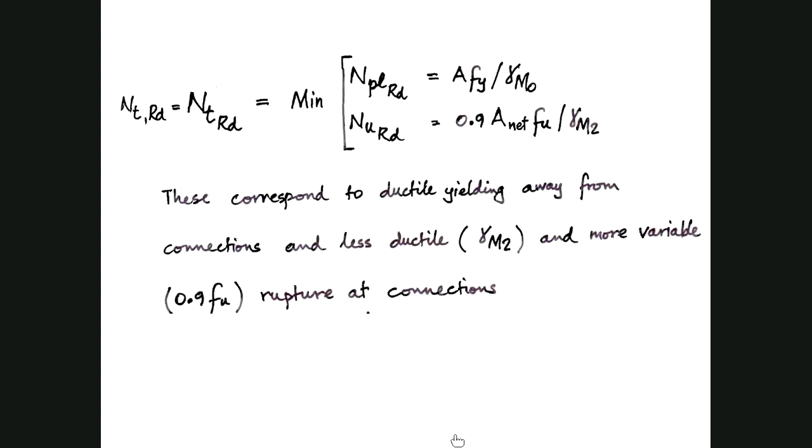Okay, so here's the first general mistake that a number of people made. In the first assignment that you did, people calculated the plastic resistance using this formula here, and calculated the ultimate resistance at the two cross sections. So the cross section basically straight down, which is one hole, and the cross section where you go staggered because of two holes, because of the staggered bolts in there. So that was fine. So that was the 3 checks that were done.